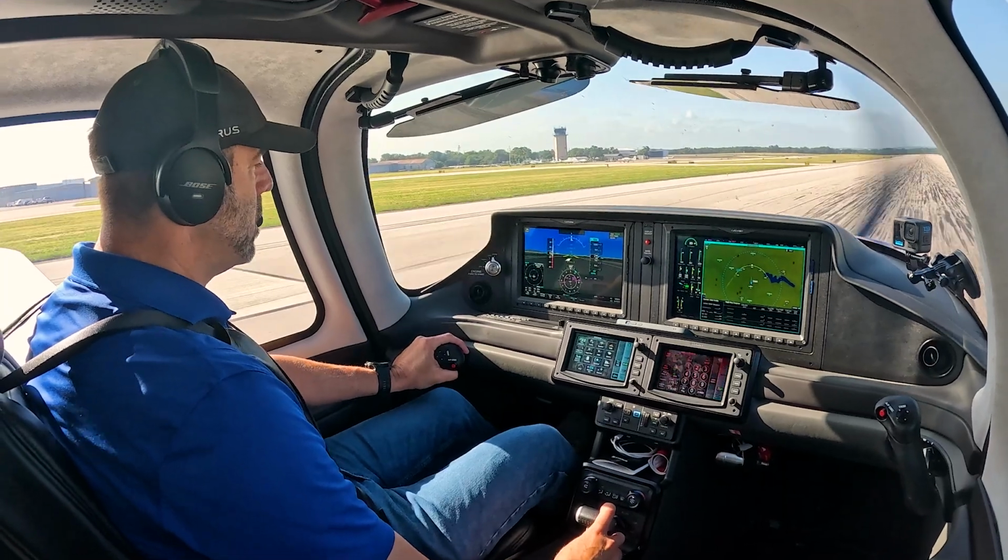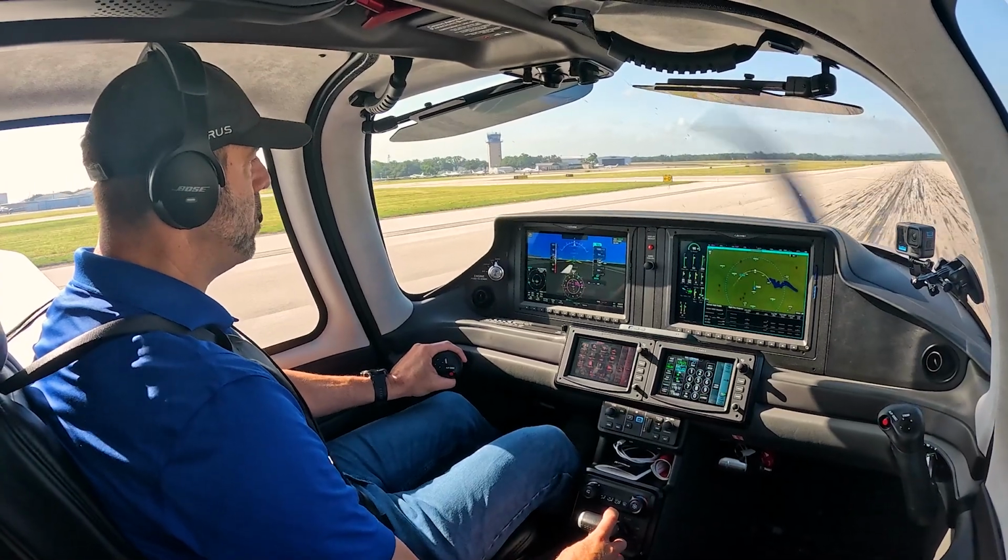We'll reduce that aileron deflection and we'll start using more of that left rudder to keep us aligned on center. Now you might be asking, how much deflection and rudder input do I need on takeoff and landing? Well, simply put, as much as required to keep the plane on center line, coordinated, and stable.